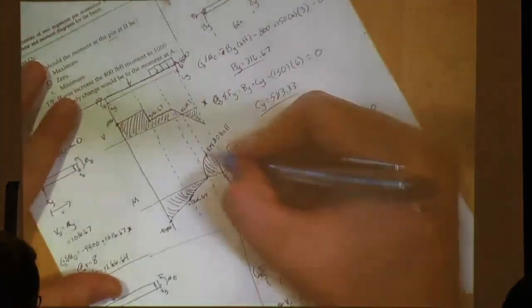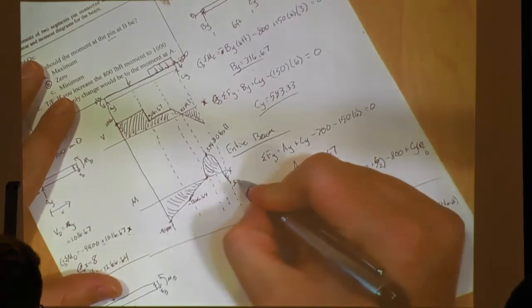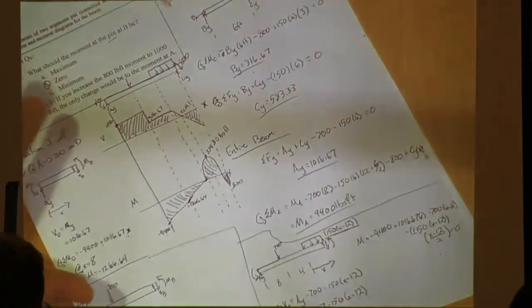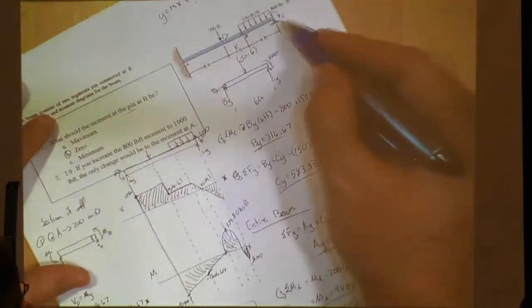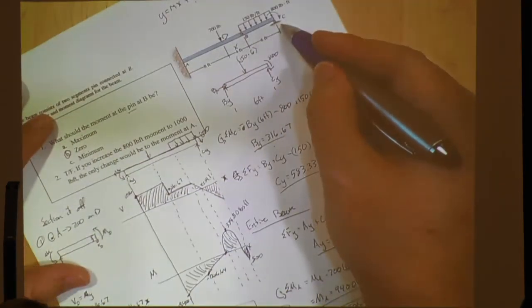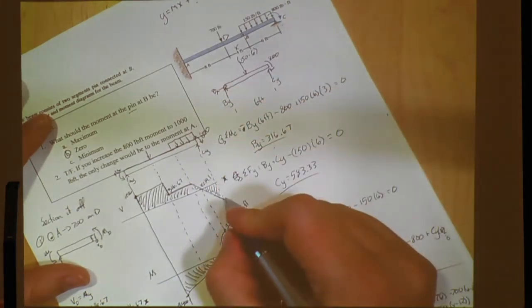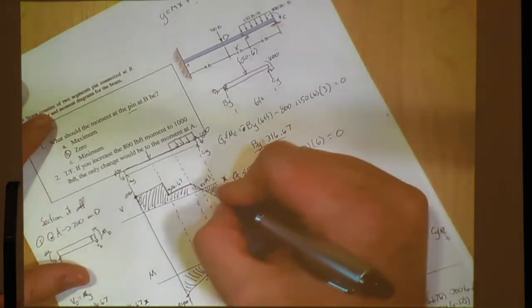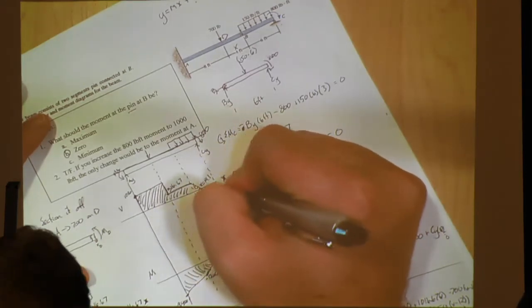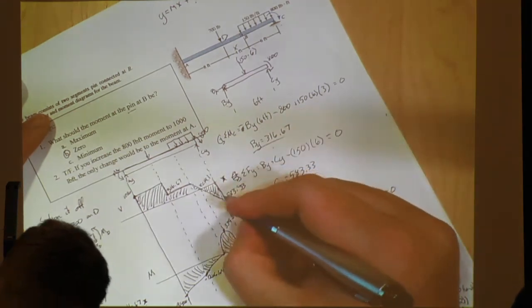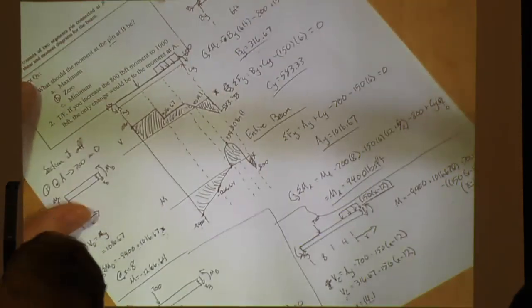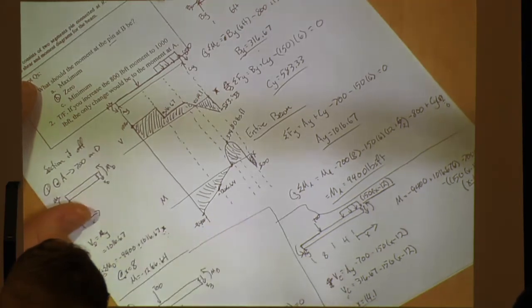So, but what do we have back here? It's going to end at negative 800, and it's going to jump right back up to 0. Well, we have a reaction force, right? So the reaction force just so happens to be the same number as it ended at. This is negative 583.33. So that means that reaction force is going to bring it back down to 0. We are static. There's no additional numbers. Everything's 0. We're good to go.